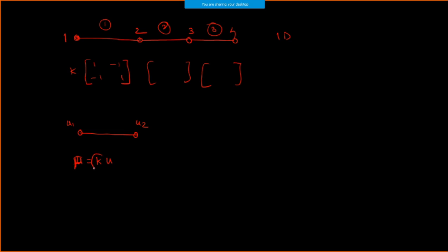So I'll get a stiffness matrix where this equation represents the displacement of node number 2. Similarly, if I look at the second element, the first equation represents the displacement of again node number 2. But this U2 and this U2 are both the same, and I need to keep these two the same in my analysis.